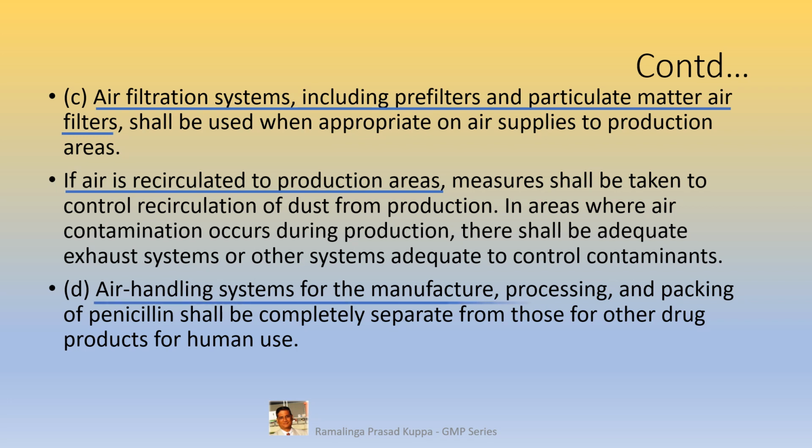Air handling systems for the manufacture, processing and packing of penicillins shall be completely separate from those for other drug products for human use. Since penicillin products are more potent, they may cause allergic reactions in some people. It is always required to have a separate air handling unit for this type of products.